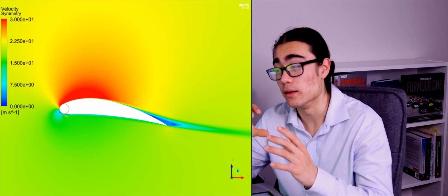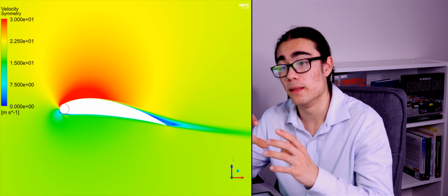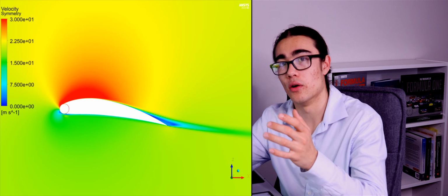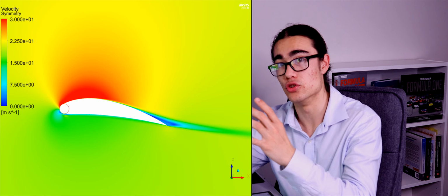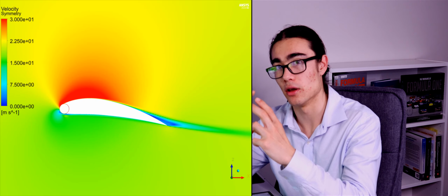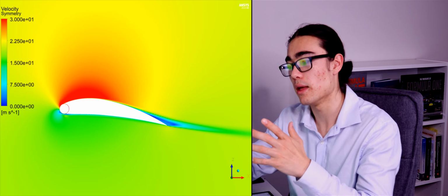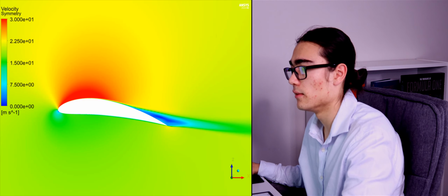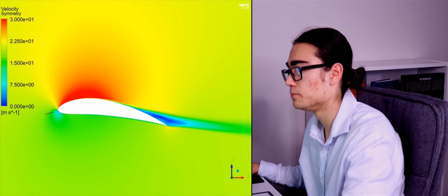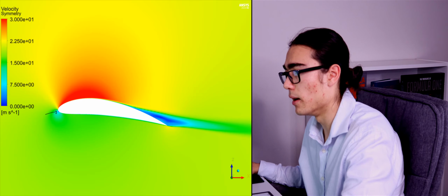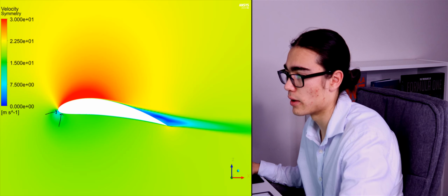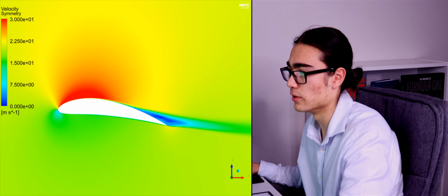The curvature is constant, which means the stagnation point is happy to be wherever on that cylinder if you just had a cylinder, because the curvature is the same. If you compare that to a normal wing, the stagnation point doesn't necessarily want to be anywhere but on this leading edge. Obviously we can put it here, but it's much more encouraged to be on that leading edge itself.